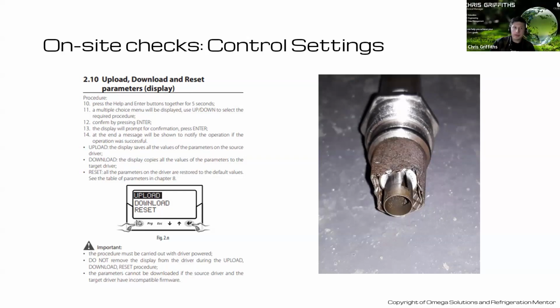Some of the end users who invest in a remote monitoring system can have it so every 24 hours it broadcasts what the site conditions should be. So even if you change a component, you can input your parameters. If they're slightly wrong, it will get that updated broadcast to take it back to what the conditions should be, ideally. That's one way, which is a good time saver as well. If you had multiple fixtures that you've replaced, you just leave it in their capable hands, assuming it is set up correctly. It saves that time-consuming process of going through and inputting 40 different parameters on every single cabinet controller.